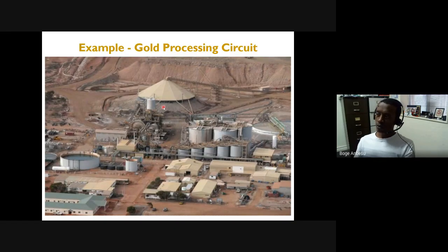Or once I stockpile, people usually have feeders at the bottom of these stockpiles, and the feeder will try to distribute the material. They may have maybe 3 or 4 different feeders at the bottom there, and they mix it up to get it to the crushing or grinding mill. So either you can take this belt or you can take this belt, but typically you would get a more reasonable homogeneity if you were to sample from here. So again, those are the things you need to think about.